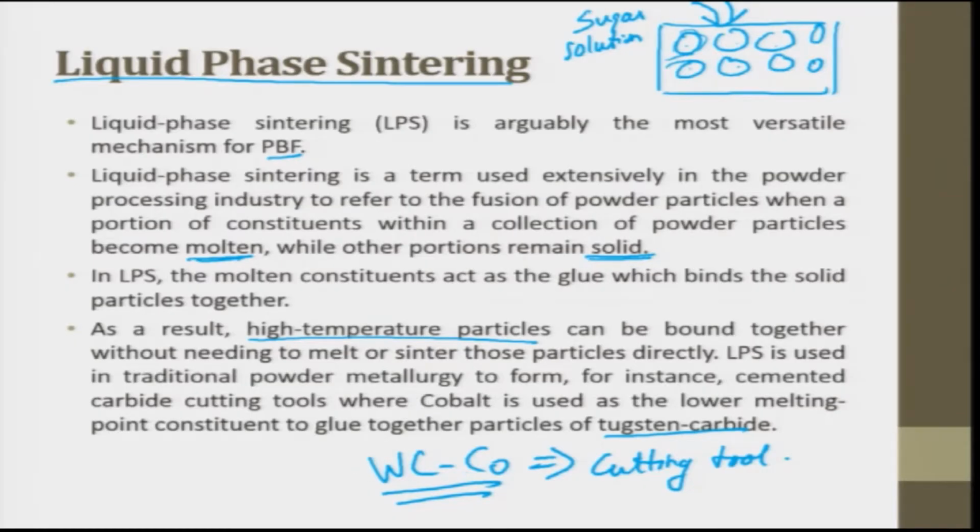It is rapid manufacturing. You just mix whatever you want, tungsten carbide plus cobalt. The cobalt content is varied depending upon your requirements. The more cobalt you add, the tougher the product you make. Once you reduce the cobalt content drastically to 1%, 2%, it will be predominantly tungsten carbide.